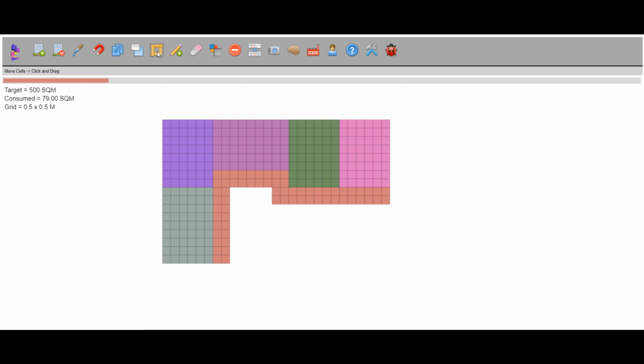Okay, now we have this measure command. So when we click here, I can measure this thing. It is like 8.5 meter by 0.5 meter. So I can understand this is like 8.5 meters. Or I want to measure how much is this. This is 3 meter by 4 meter. This is 1 meter width corridor and 5.5 meter. This is just a measuring tool. I can measure the entire space. It is like 13.5 by 8.5 meters and 44.28 feet by 27.88 feet.